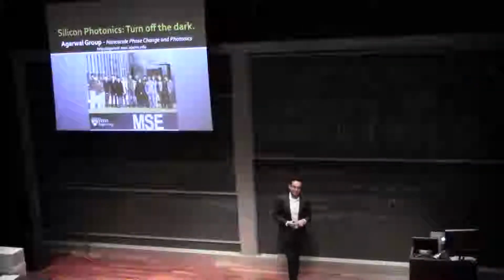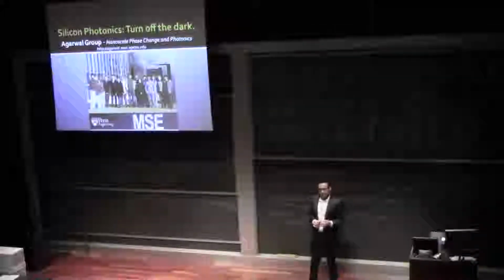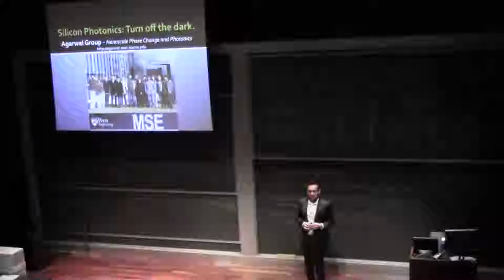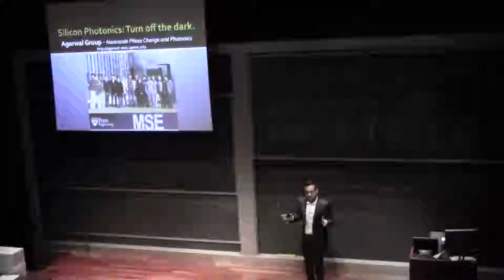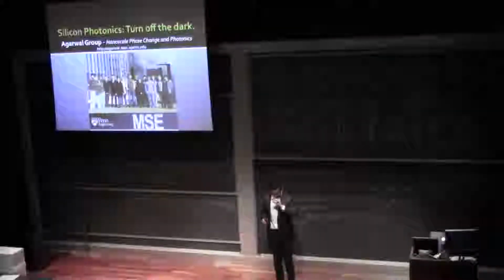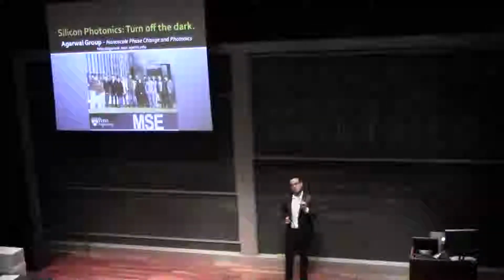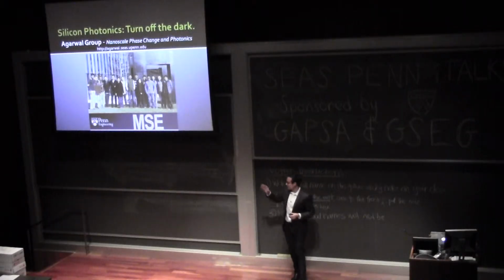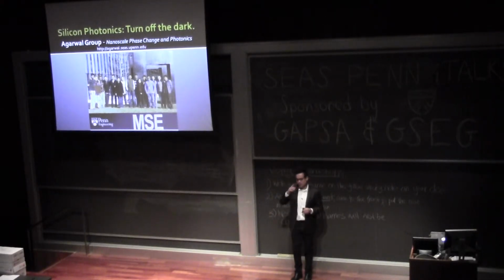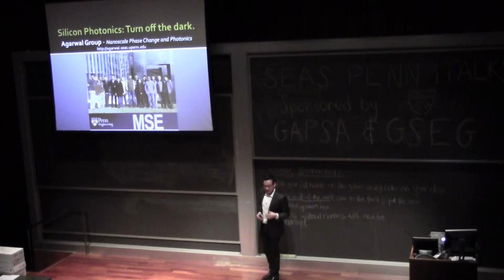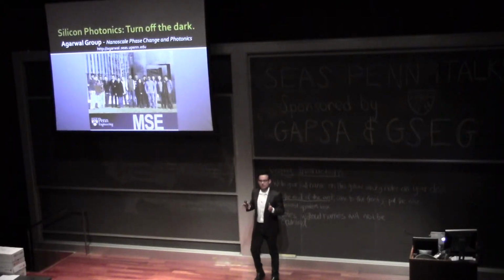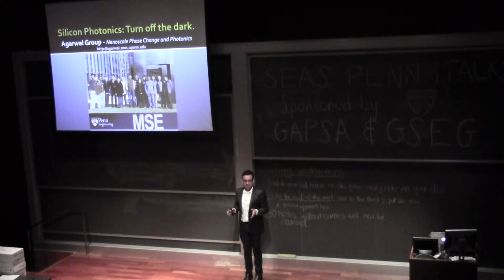The coating matters, and I said that on purpose, because we're designing optical antennas. So the resonance frequency of that optical antenna, the region in the electromagnetic spectrum where it's actually active, is very strictly dependent on the geometry of the antenna. I showed you some very nice pictures. These are actually computational simulations of the VNM. And I use these simulations to design optimal optical antennas, optimal geometries, optimal thickness, that would make my antenna active in the region where my semiconductor emits light, in the visible range.